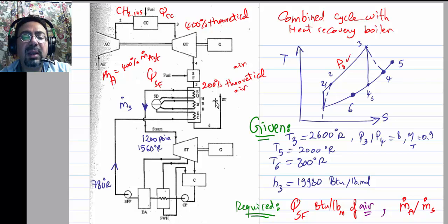First law of thermodynamics again, right? In this course, most of the time you are basically just applying the first law of thermodynamics in most problems. So in order to get this Q, that Q will be m dot multiplied by delta H, H5 minus H4. So we just need H5 and H4 and we'll be in good shape then. So let's see what is given to us.